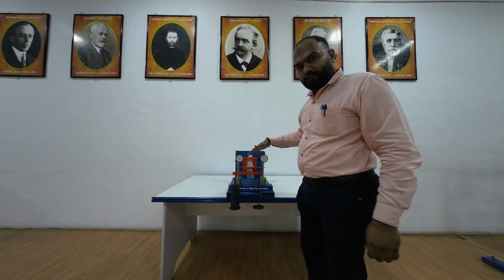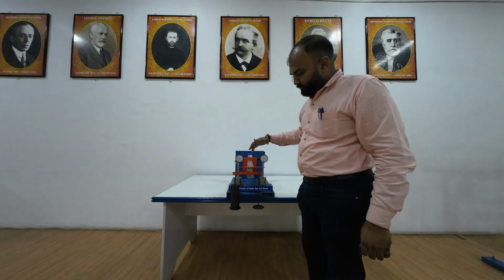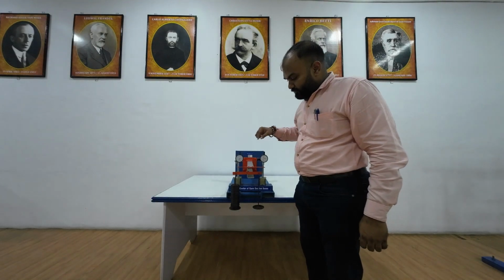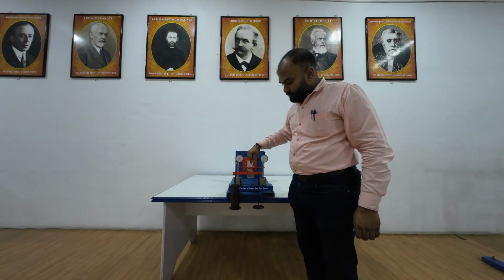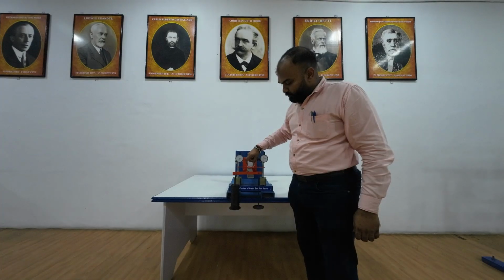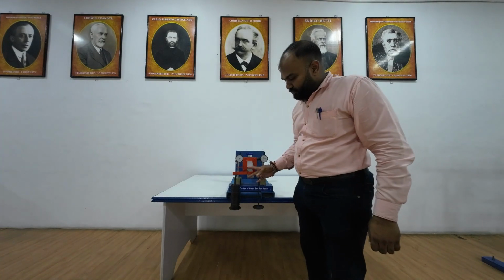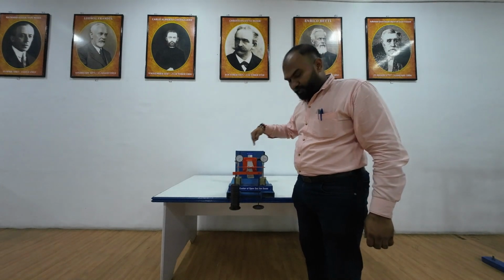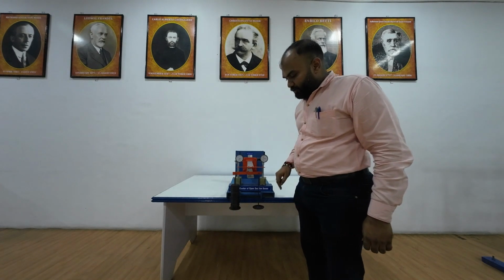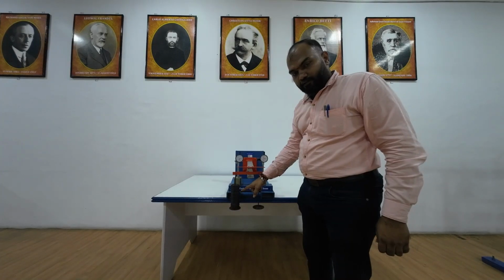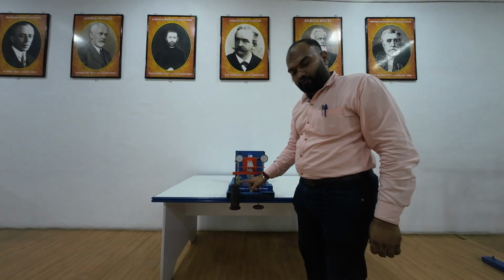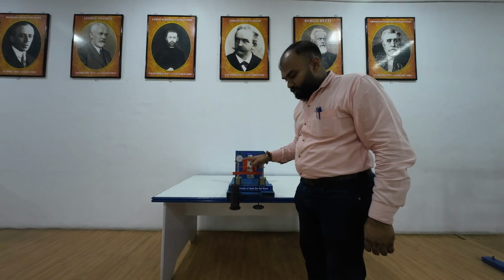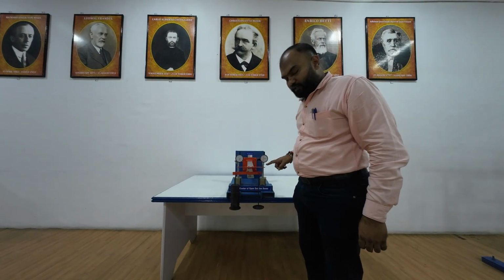Here we have an experimental setup for finding shear center for an open section. Here we have a C section. The C section has 2 mm thickness, and then this is about 5 centimeter and this is about 7.5 centimeter. We have 2 dial gauges on 2 ends. We will be having weight hangers, and we will be placing weights on one side, and then we will start measuring the displacements on these 2 points.